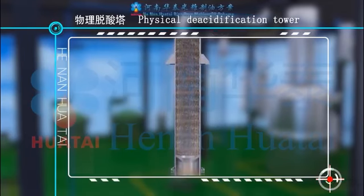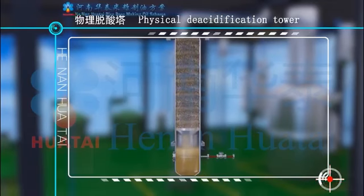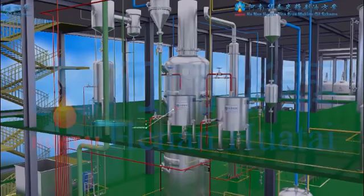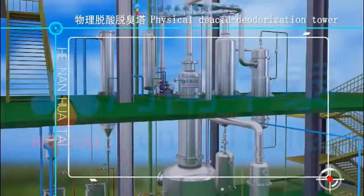Fatty acid vaporizes inside the tower. The fatty acid gas is extracted by the vacuum system and sent to the condenser for condensation recovery. The deacidification oil is conveyed by the oil extraction pump to the conduction oil heater to get secondary heating, and then transported to the physical deacidification and deodorization tower.